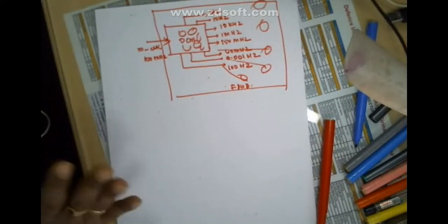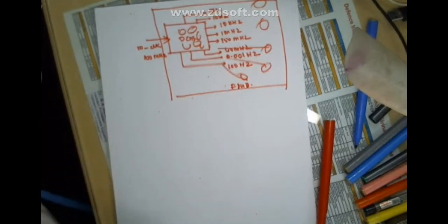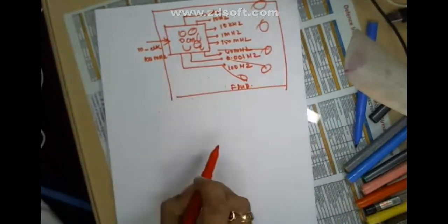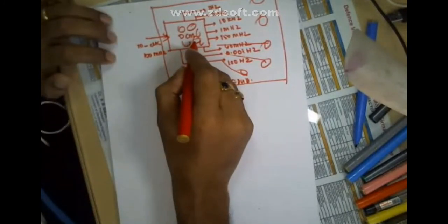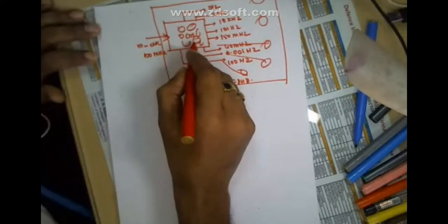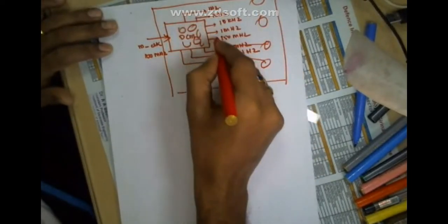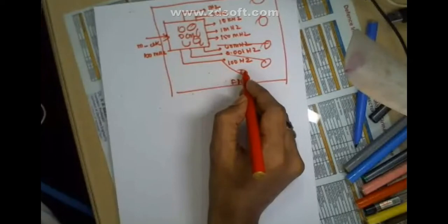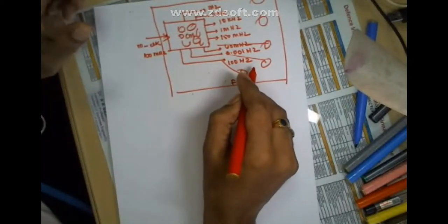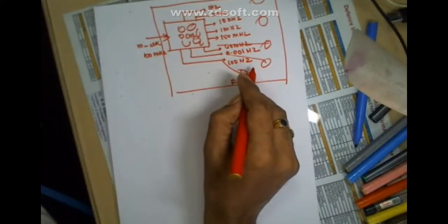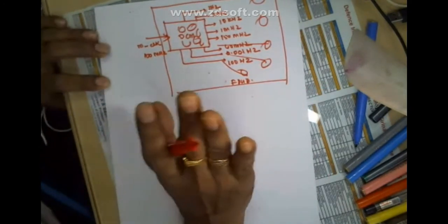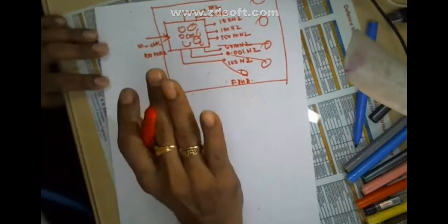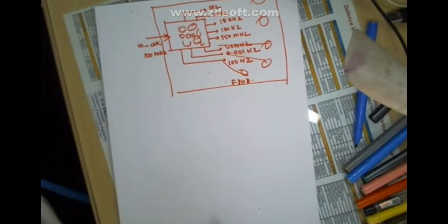Sir, are the types of clocks the DCM generates fixed, or variable according to the peripherals? According to the peripherals, you should generate it. It is variable. It is completely user controlled. You can design any clock. Nothing is defined there, but the procedure is defined. Based on that procedure, you can generate any clock you want. The number of clocks is also user defined, and the speed of every clock is also user defined. For example, you can generate 50 clocks, 100 clocks, or 10 clocks.